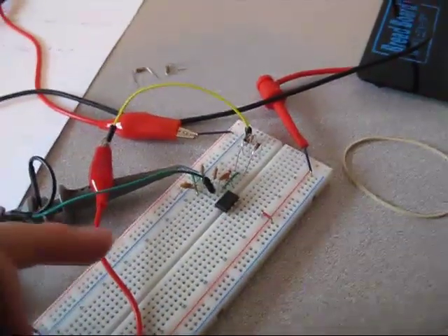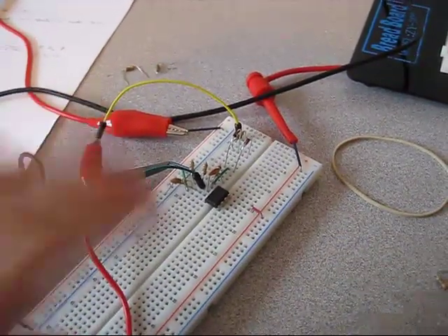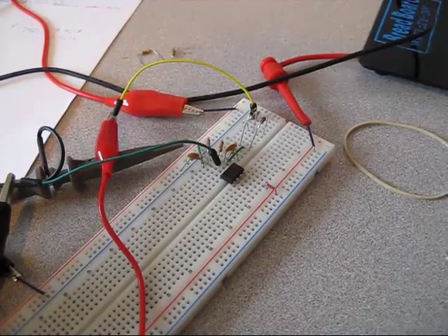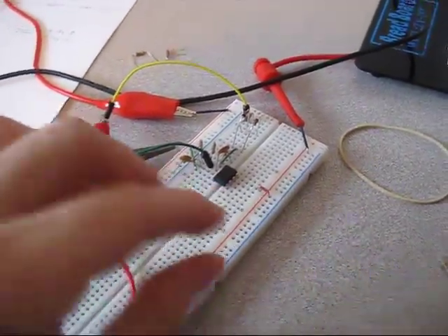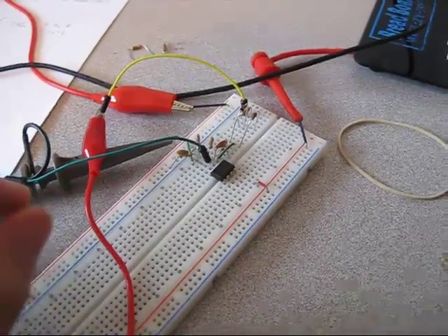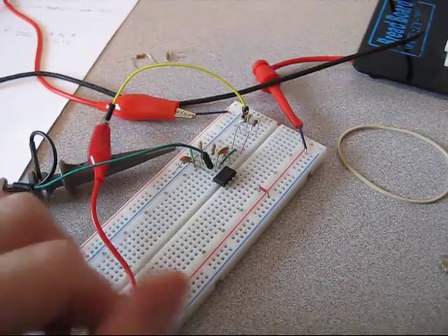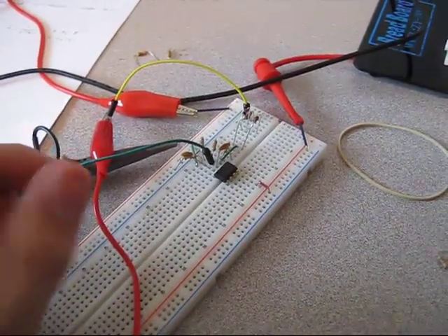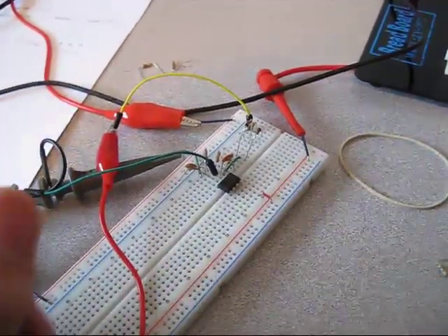So you can put in digital pots. You can make this digitally controlled if you wanted to adjust the frequency, and that'd be kind of cool. Of course, again, you'd have to calibrate them so that both the resistors would be the same. So you'd put in a small trim pot to be able to match the slight offset that one pot has to the next. But that'd be pretty cool.